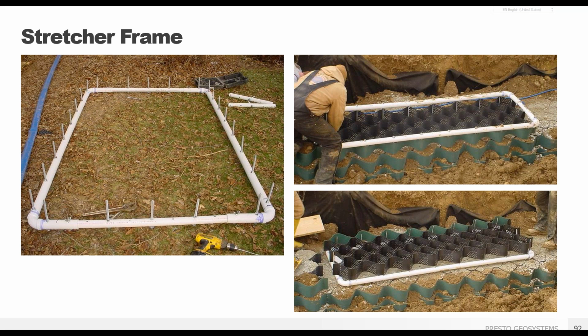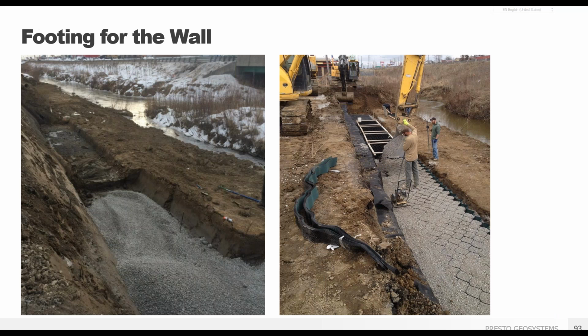Now let's see the steps of a GeoWeb earth retention system being built as part of a vegetated stacked channel. Preparing the footing for the GeoWeb wall. And on the right, you see the footing layer of GeoWeb installed with granular infill placed. And you see the stretcher frames and infill process. A pro tip is to have a portable compactor on level with your build and compact as you go.